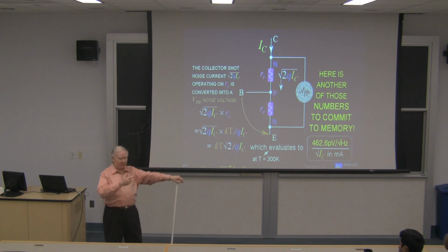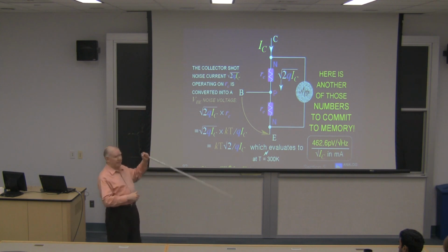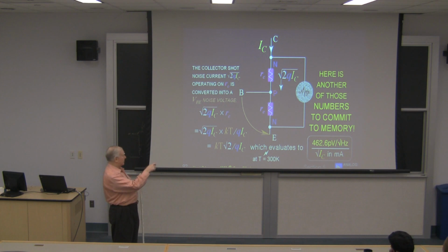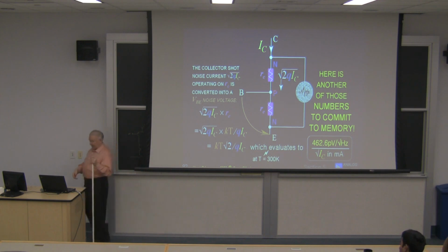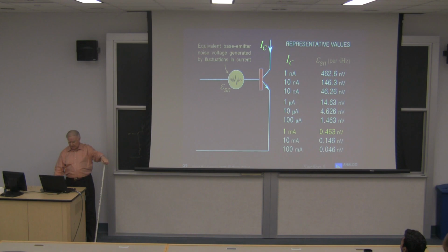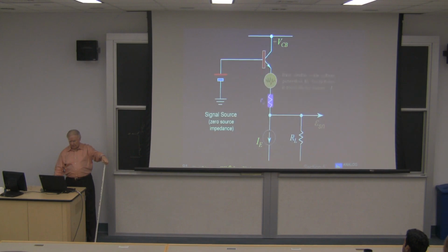Because as you go up in tail current, this component of noise goes down, but the base current component goes up, being shot noise times the source resistance. So that's all in the notes, I guess, though I shouldn't call them notes, these are the slides. I think I've probably labored some of these points well enough now to call it quits.